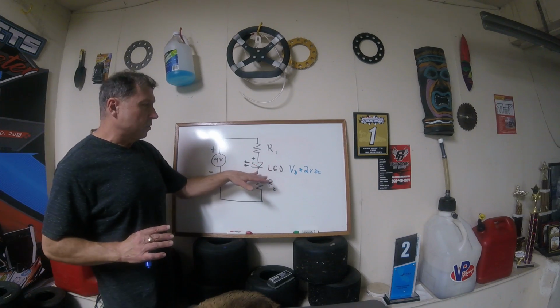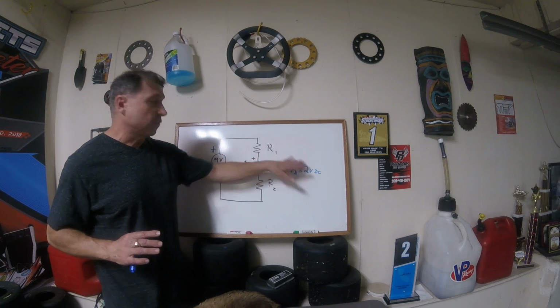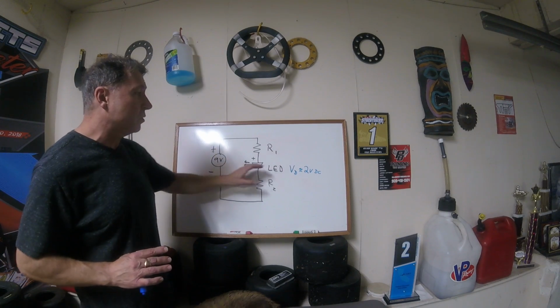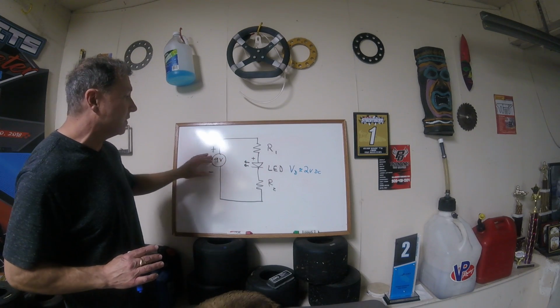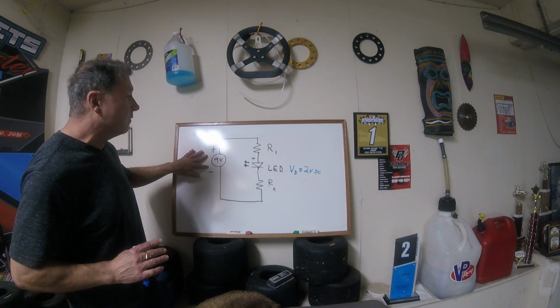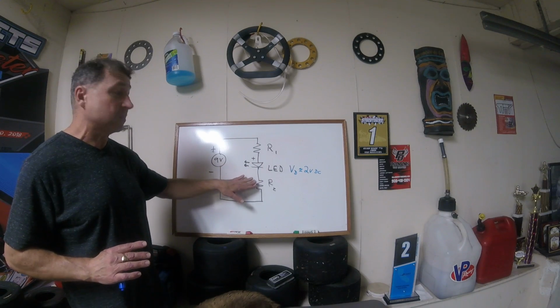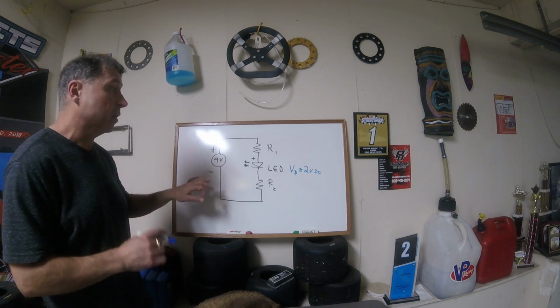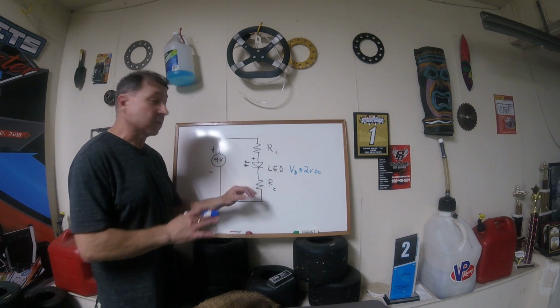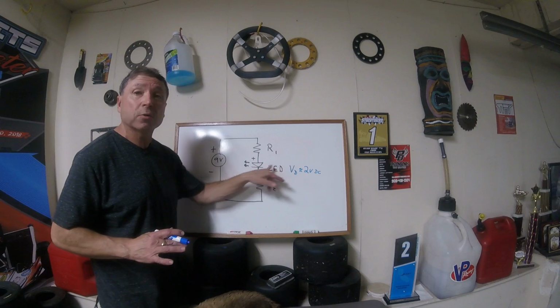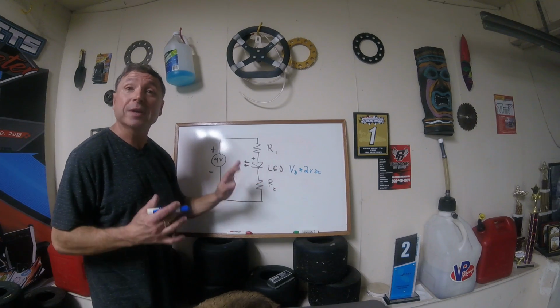The easiest way to do this, because of this constant voltage device, is to mathematically take the 2 volts away and say that only 7 volts is applied across the 2 resistors, and we can solve the current that way. It's much easier solving the current through basic resistors with Ohm's law than it is to use a logarithmic function to solve the current through a diode.